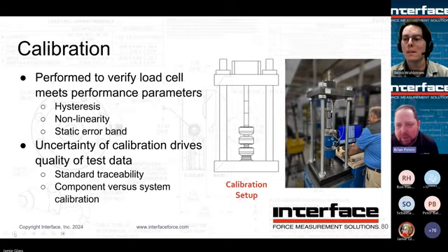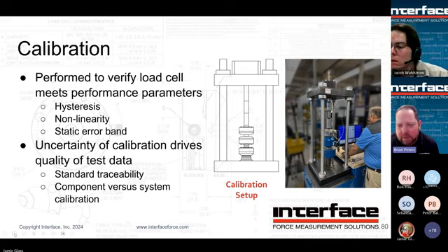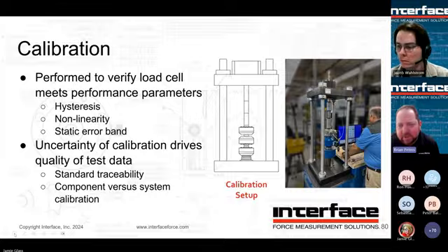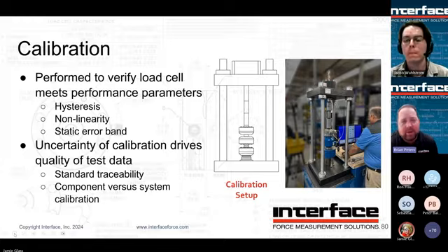Sorry, I'm muted. While we're talking temp comp, there was another question here, Jacob: temperature compensation appears to assume the entire load cell is at a constant temperature. Is that accurate? Yes, that's fair and accurate. There is temperature compensation performed in a specific area on every load cell in terms of where we can get to it in the manufacturing process after we complete the bridge.